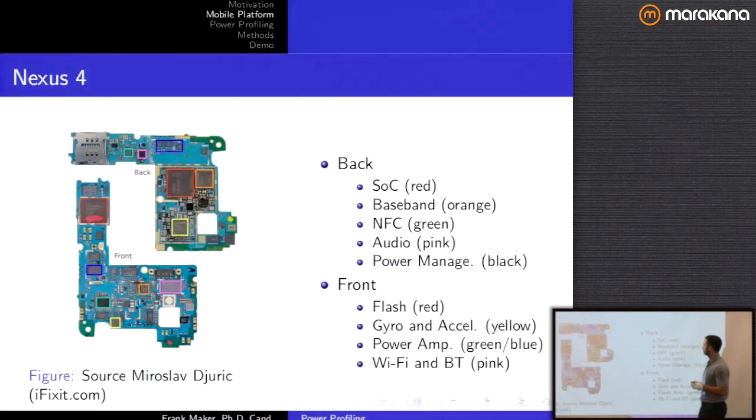Okay, so now we'll lift the hood a little bit, give you an idea of what's inside a smartphone. So inside a laptop, you essentially have a big processor. I don't know if they still have Northbridge and Southbridge as separate chips, but there's not that many chips anymore. Most of it's been sucked right into the general purpose processor. And the reason is because almost everything's done in software. Your audio is done in software, video is done in software. Almost everything that can be done in software is done in software. But on a smartphone, because you only have this 3 watts to play with, they break out some of the more energy-intensive functionality into ASICs, application-specific integrated circuits. So basically, application-specific chips.